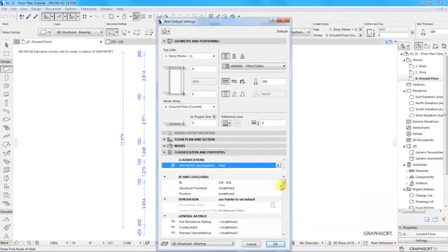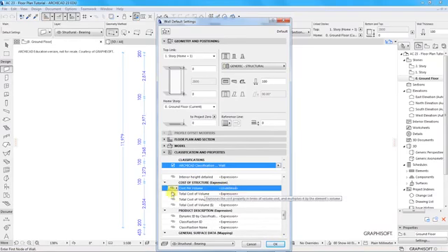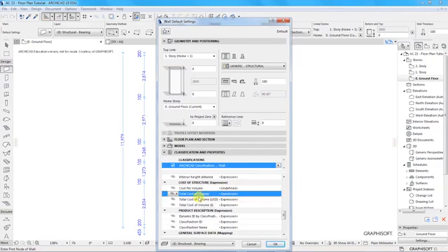There are some properties here. There are Archicad classifications, categories, structural functions, positions. There is data such as fire resistance rating, thermal transmittance, sound transmission class. There are other details such as construction type and technology, and environmental data such as the life cycle environmental data, stored energy, service life, and all this other information that you can see down here as I continue to scroll down. So you can see cost of the structure as an expression. You can customize that, and total cost of volume, total cost of volume in US dollar. This is all in terms of expressions, something that you can customize.